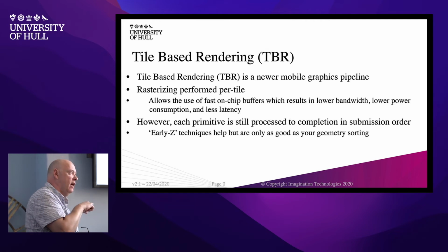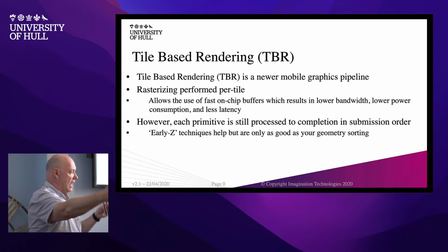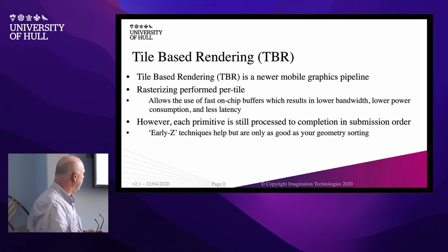And the beauty with the tile-based system is you can scale that up. If you've got 4 of them there, then you can process 4 tiles at the same time. If you then later on have it so you can process 8 tiles, then you can do it twice as quickly and so on. So it's a really nice scalable architecture.